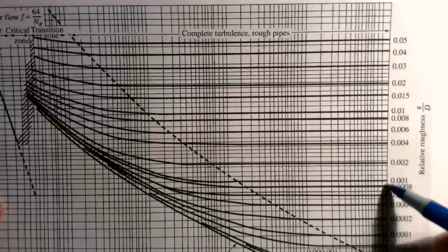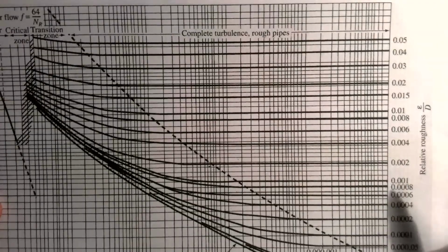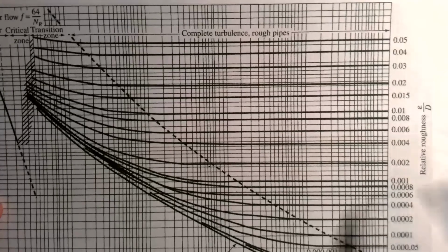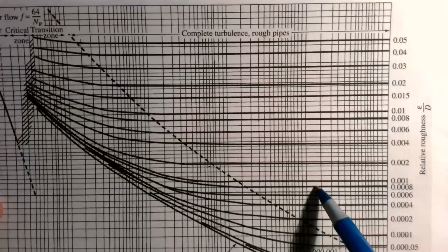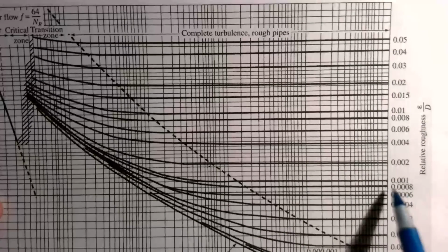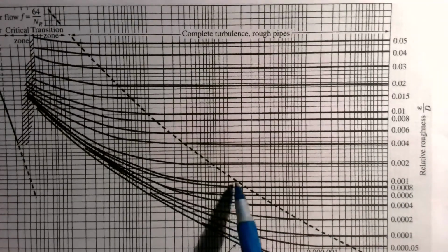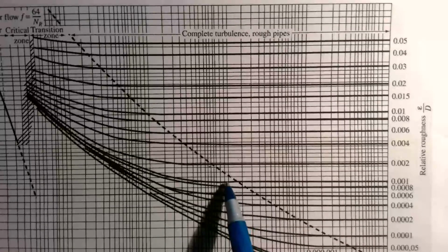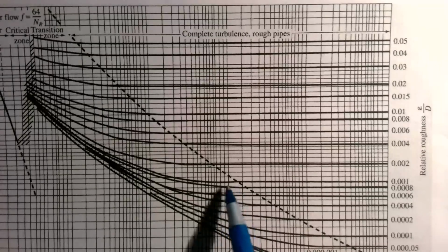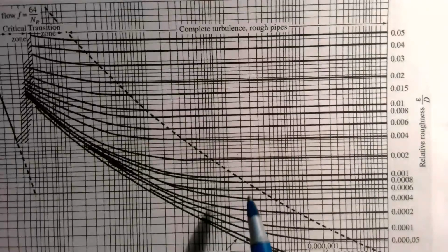So it's kind of like between these two, right? Yes, it's almost 0.001. So it's right in there at just under 10 to the 6th. So if we look here, basically we are still at the fully turbulent regime. I mean, it is technically on the left side of the line. And so you might want to update it and then redo all this again.